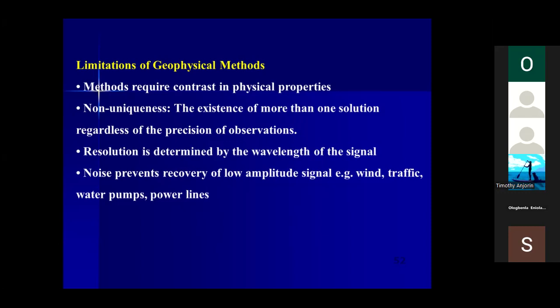Yes, resolution, depth of penetration. For you to be able to penetrate deep, we use the contact method. And you usually have better resolution. But we also use the non-contact method for our reconnaissance survey because it enables us to cover a large expanse of area. It does not require so much personnel, okay? And it can now give us an idea of where to concentrate so that we can get detailed information.